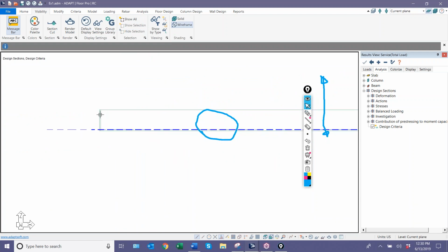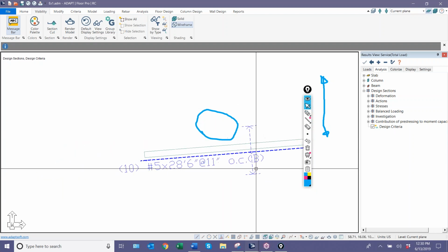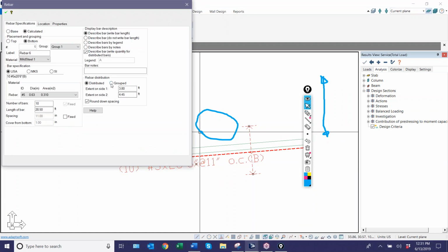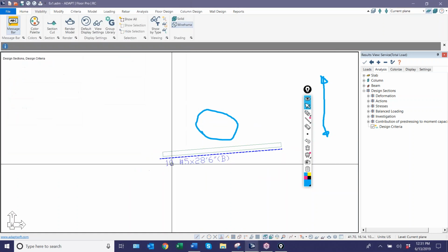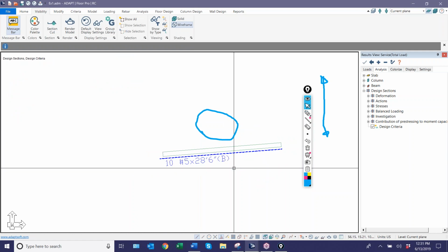So you can see the bar is set at the effective depth of that beam, not the slab. So these bars truly are being designed to be in the bottom of the beam, but because of the two-way slab criteria, they're shown as distributed. I could group them, but that doesn't help. You kind of have to know what's happening before you make a change to, let's say, grouping the bars. I could double click and say, well, I'll just show them as grouped, but they're still shown graphically out of the beam. So how can we make this more direct?